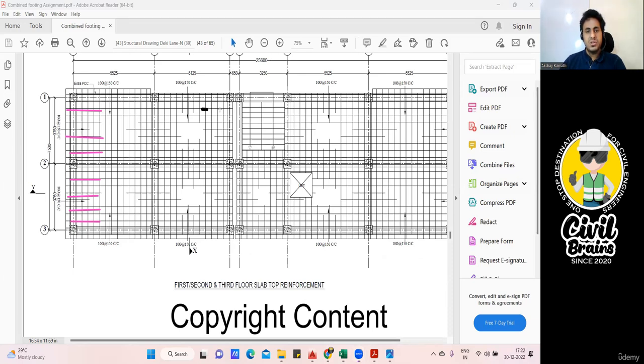I'll find the cutting length for this bar, this bar. Same thing, okay? Again here, the bar won't be like this. Remember, the bar will again be something like this. Like this, the bar will come up to the beam and then that red color portion, your development length, will come. It will get like this. Got it, no? This is on this side now. Fine.